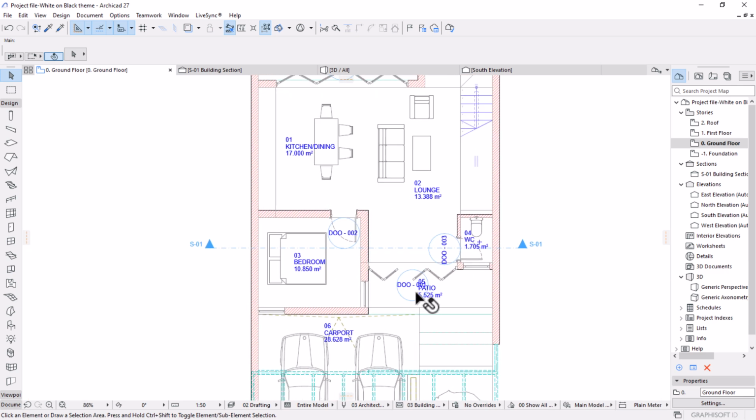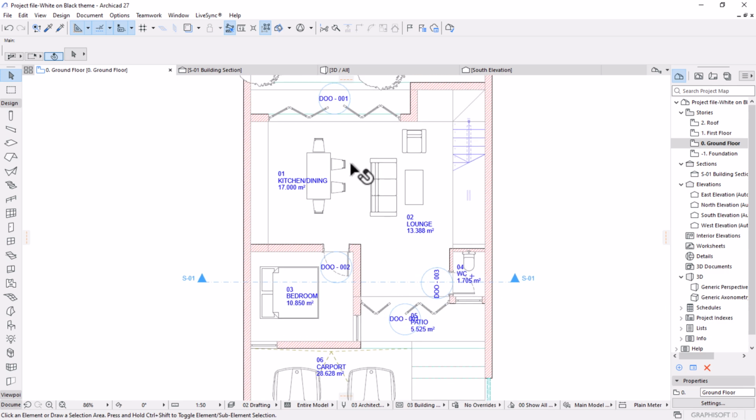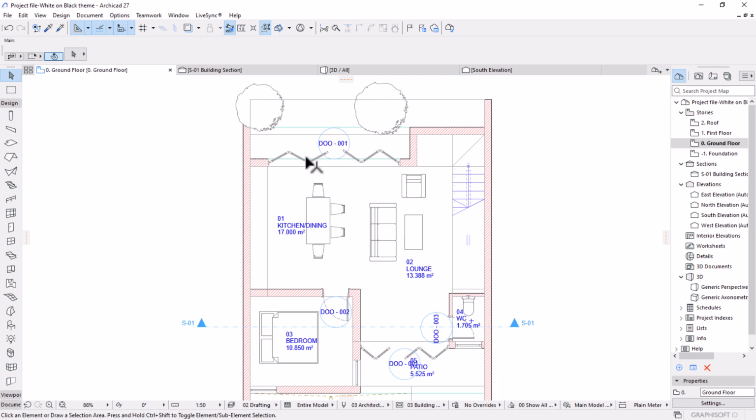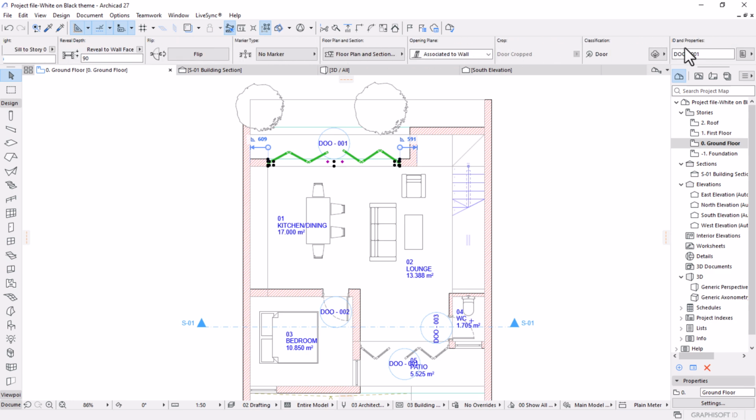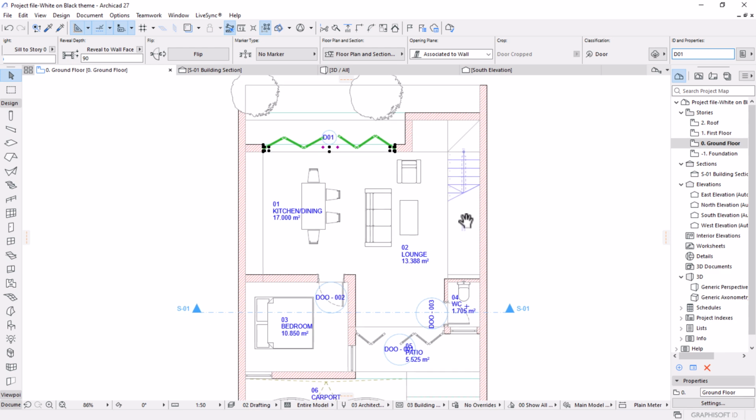That's what we have. We can do the same to windows as well if you want. Okay, so I could go ahead and also optimize the IDs for our doors. For example, if you look at this door, it's D000. It has a lot of funny weird zeros. So you can select the door like that and then scroll here on the info box. Let's find the ID property. We can reduce the code into 3 characters like that.